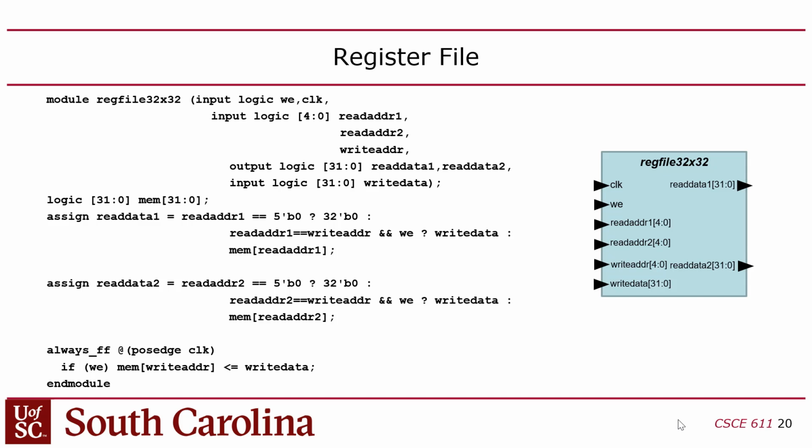It would take a whole cycle to read them, and then you'd have to wait until the next cycle to do anything with them. But if the reads are asynchronous, you can access the registers and then do something with them in the same cycle. That's the difference. In this class, we want to resolve branches, and we're going to do the execute, meaning whatever number crunching operation the instruction requires, in the same cycle that we read the registers.